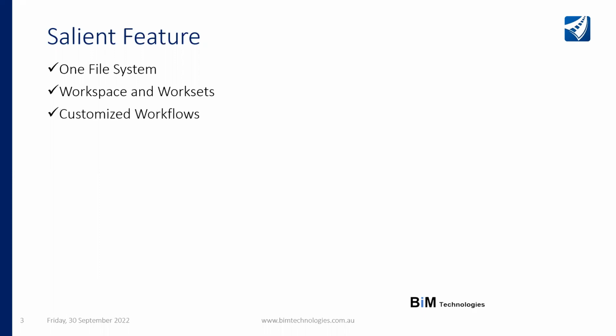So it comes with customized workflows. When you start OpenRoads, you will see multiple workflows already created. Workflows are basically the arrangement of tools and settings required for a particular kind of work. Let's say you're doing drawing work and you select a drawing workflow. It will show you all the tools required for drawing and hide anything unnecessary. If you select the OpenRoads workflow, it will bring all the tools in front and hide everything which is not required. So this is how you can create more space while doing modeling using the customized workflow.